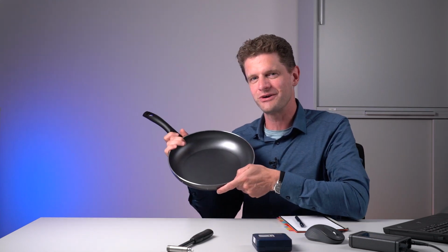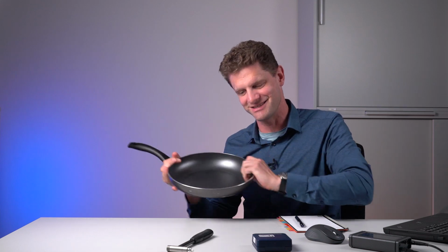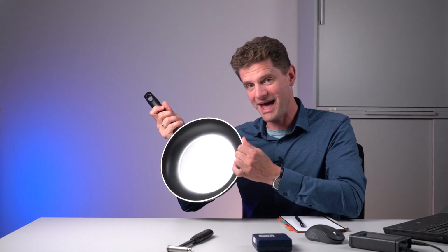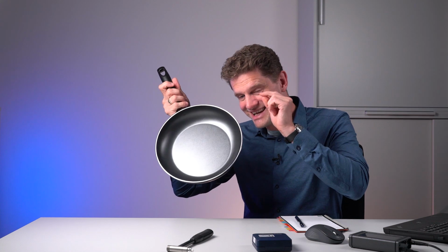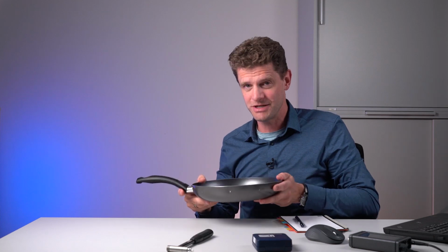And that's what we want to see. But as we hear, I can hear the tone. And that's different to the example I showed in the previous videos, where it's just a mass about 1 or 2 hertz. Now it's about 300, 400 hertz, because the masses are very small and the stiffness is much higher than the spring. So the swinging motion of the pan is very tiny and very fast, so I can't see it with my eyes. So we need measurement equipment.